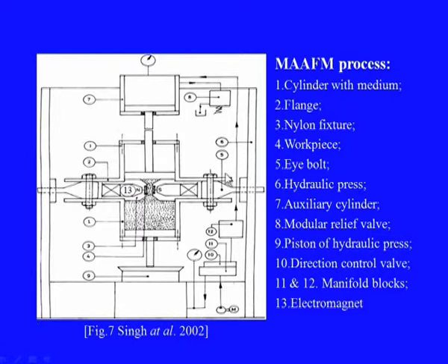The magnetic field increased the resultant cutting force on this surface because of the change in the incidence angle with which the particles impinge upon the surface. So, this is the complete setup of this process with different hydraulic diagrams and different other components for measurement of different parameters like flow parameters, pressures and so on. This has been incidentally developed in IIT Roorkee again.